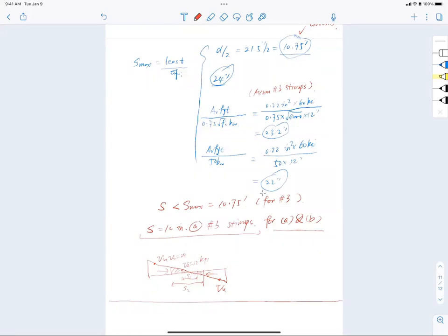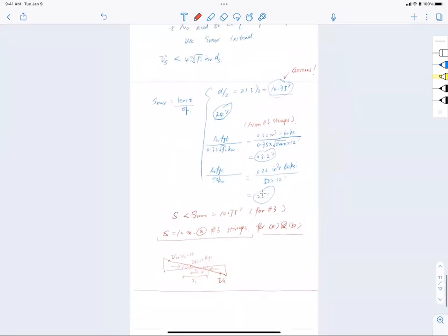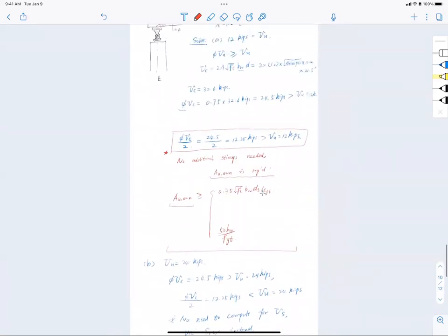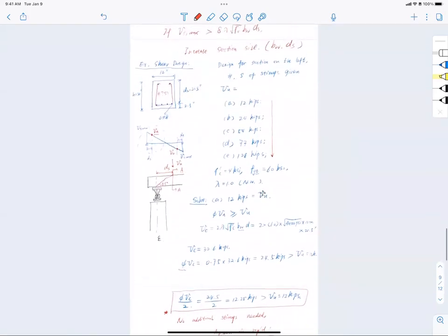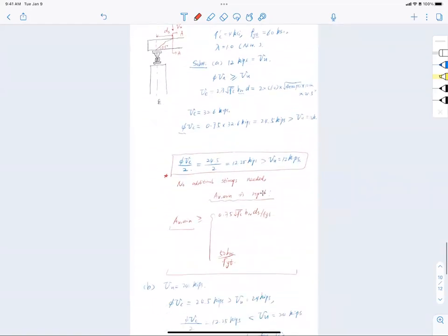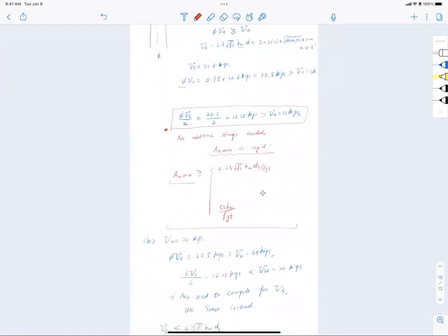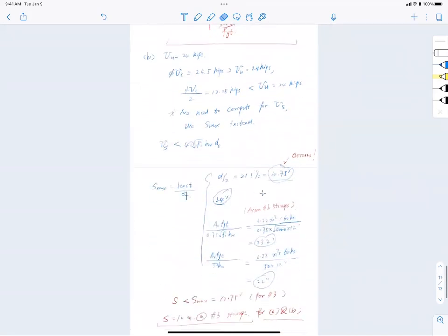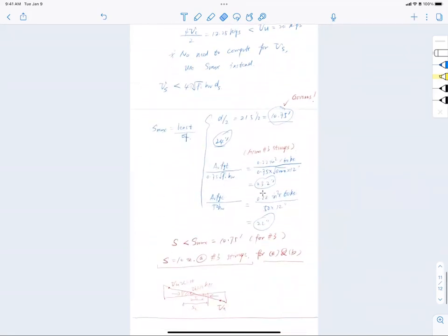Now my time's up today, and I'd like to quickly sum up because I don't want to get into the second one and third one and not finish. So take a quick look at what we have done. As applied shear increases, our stirrup requirement increases as well. In the beginning, barely anything will work; just throwing in some steel should satisfy the requirement. Then afterwards, you start to have some requirements, and you can use a higher requirement to cover the lower end. The cost is that you add more materials, but the benefit is that you make the construction easier.